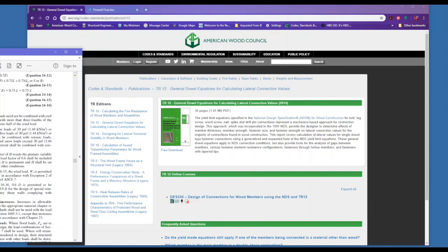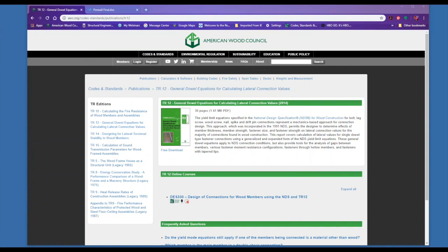Hopefully that makes sense. And then another question came in regarding the firewalls and allowing diaphragms to go through in high wind zones. So this provision of allowing the diaphragm to go through is just for seismic design category D, E, and F. And if you're in a high wind zone and you're in those design categories, then the diaphragm can go through. But if you're in lower seismic, then per the letter of the code, it's not allowed